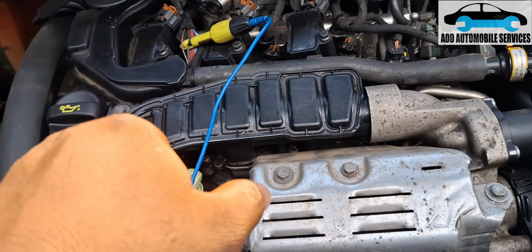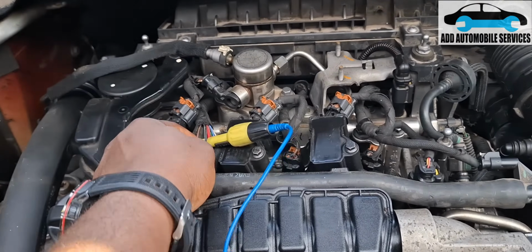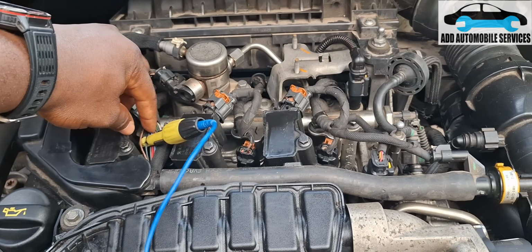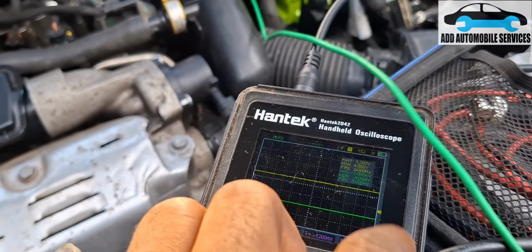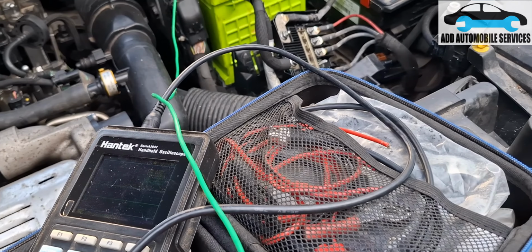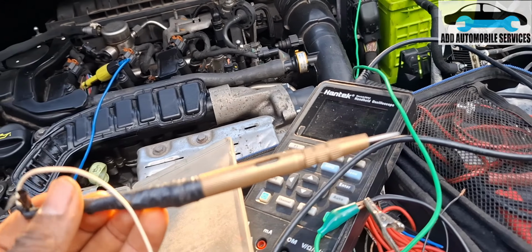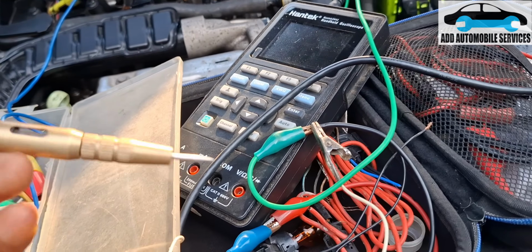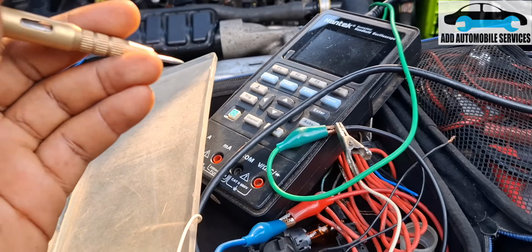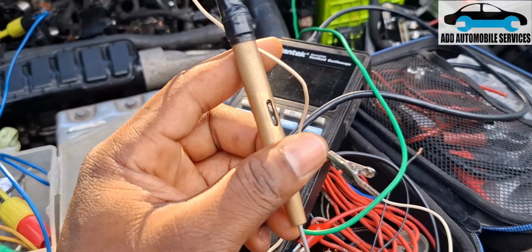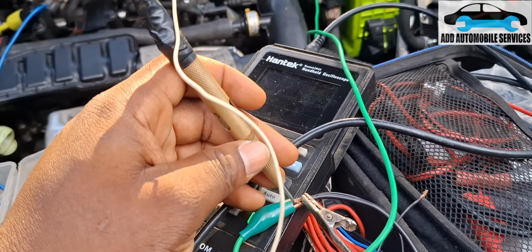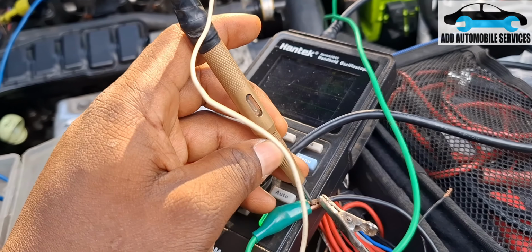I've traced from the oil pressure sensor to this point, and I have the brown, the gray, one white and one red and white. If you can see, I'm having 5 volts. To test a 5 volt signal wire, you use this incandescent test light. You connect one side to battery negative and test it, because this test light is rated from 0 to 12 volts. I'll test it, and it should be able to turn on.